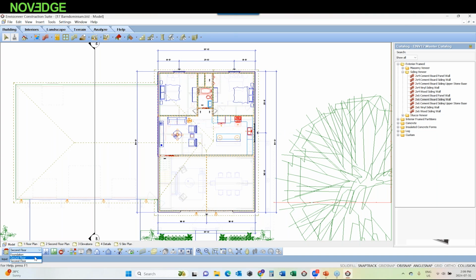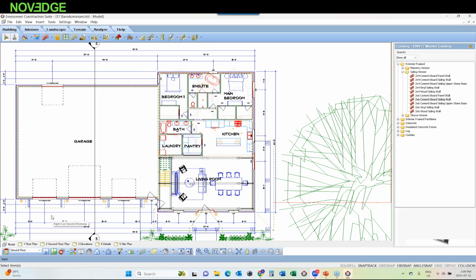So when we look at that model, we can start to do different lighting and layout, all the different electrical items as well. So we can put in all of our outlets. So if I go to auto place outlets, it will look at the different rooms and say, do you want some in this room? And it'll start to lay them around the different rooms based on the code that I told it to follow for this particular model itself.